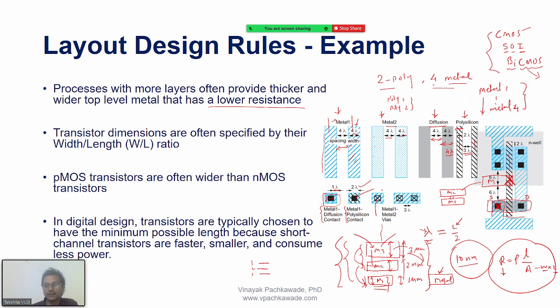So, for example, this shows metal 1 and metal 2 connected with special contacts, they are called vias, and they look like this. So here is how I am making the connection. This is a cross section, and if I look from the top, they look like this. So you see now there are two metal layers. This one is shown by these arrows, and in the same diagram I have these dots. So this is this layer.